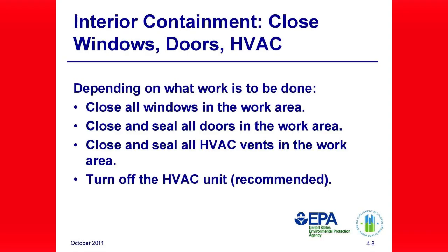For dusty jobs, it is strongly recommended that you seal work area windows with protective sheathing to prevent dust from getting into the troughs or onto the sill, making it harder to clean. When sealing windows, cut plastic sheathing layers slightly larger than the window that you are covering. Attach the plastic sheathing with tape over the window to completely seal it. Make sure that the tape or the sheathing does not cover part of the area in which you are working.